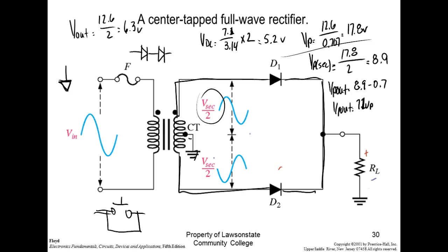So you got to be real careful, and this gets people in trouble. The black lead on your meter is a meter reference. Where can you put the black lead in your circuit? Anywhere. As soon as I connect that to any place in a circuit, that is ground. So if you hook it up into a grounded circuit and you stick this inside the circuit, then you've got a short circuit, right? You understand? So this is the right symbol. Why is it the right symbol? Because this is ground. So I've reestablished my ground.